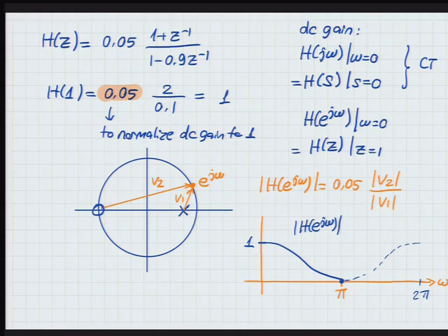And in fact, here, I just want to give you concrete coefficients, but we could make this a lot more general if we left the pole as a parameter that we can decide. There is good reason to leave the 0 where it is. What is the reason? Yeah, because we want our response to be 0 at pi, right? So negative 1 is e to the j pi. So we left the 0 there exactly on the unit circle. There is no harm in putting zeros on the unit circle.